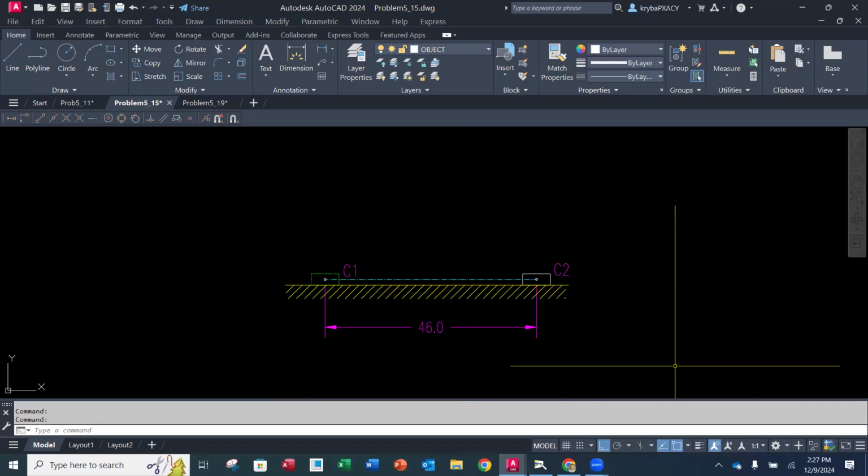The only thing that this problem is telling us is that we have a Q of 1.37. So we know, first of all, it's offset. It's not going to be an inline slider crank. It's going to be an offset slider crank. But we also know that the output stroke is going to be 46 millimeters. So the first thing you want to start with is the stroke, because this is our end result of the motion. And then we're going to work it backwards.